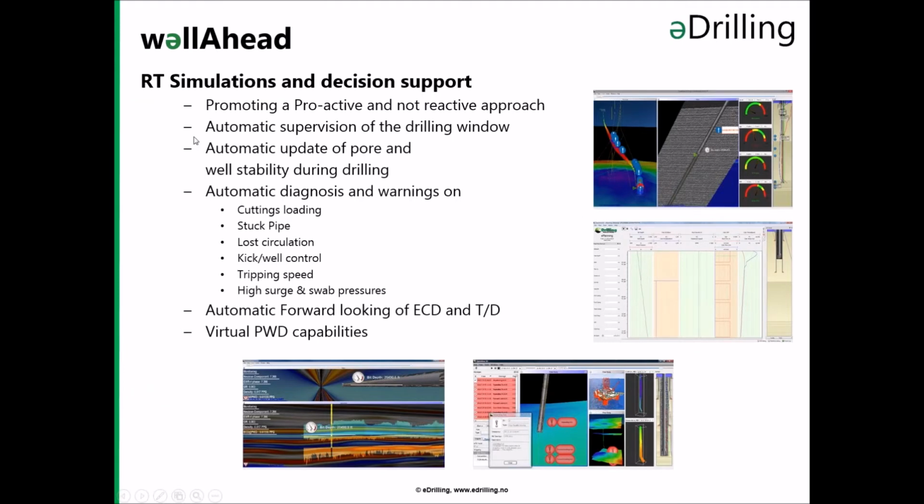It also makes automatic supervision of the drilling window. You can automatically update pore pressure and wellbore stability during drilling, and it also provides diagnostics and warnings on a number of key parameters which are related to the technical quality and also the safety of the wellbore.